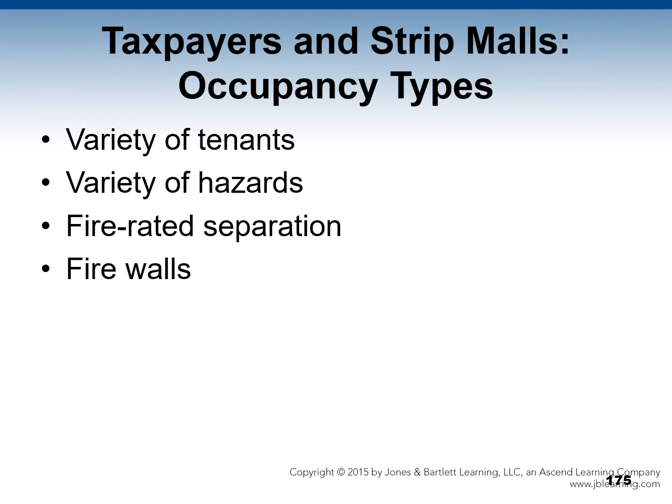Strip malls of Type 3 and Type 5 construction that use combustible structural roof require the use of draft stops to compartmentalize the attic or floor void spaces. Draft stops are required to limit the size of attic compartments to 3,000 square feet and floor void compartments to 1,000 square feet. Installation of automatic sprinklers can eliminate the requirements for draft stops. Some building codes require fire stopping at a maximum of 20-foot intervals in combustible architectural trim.